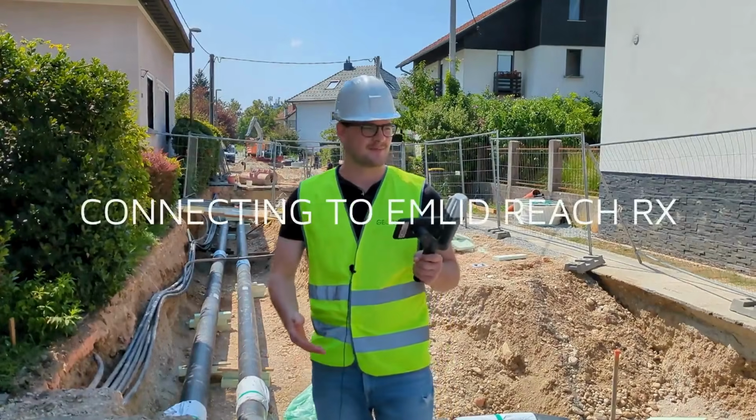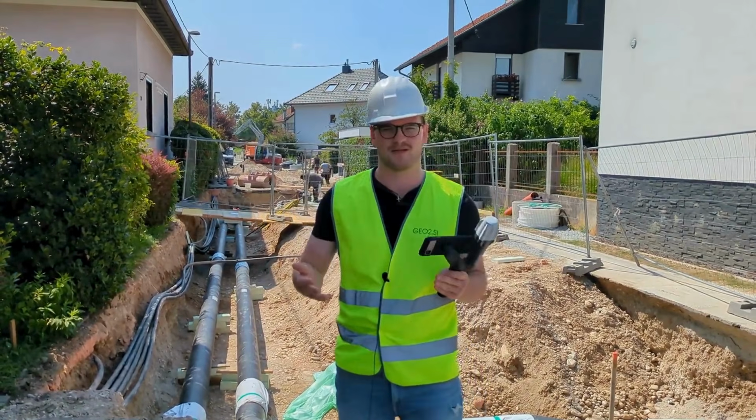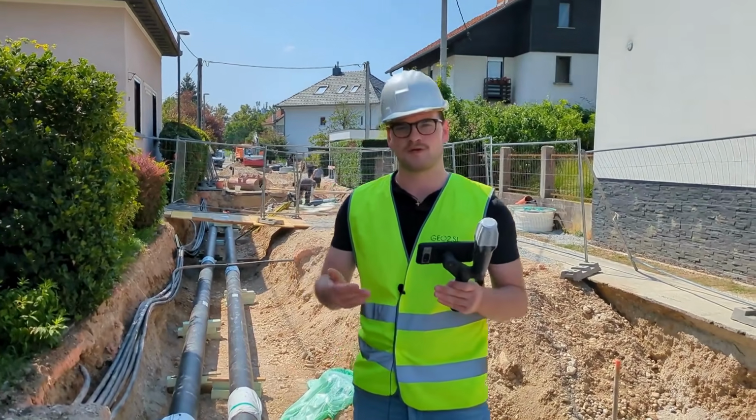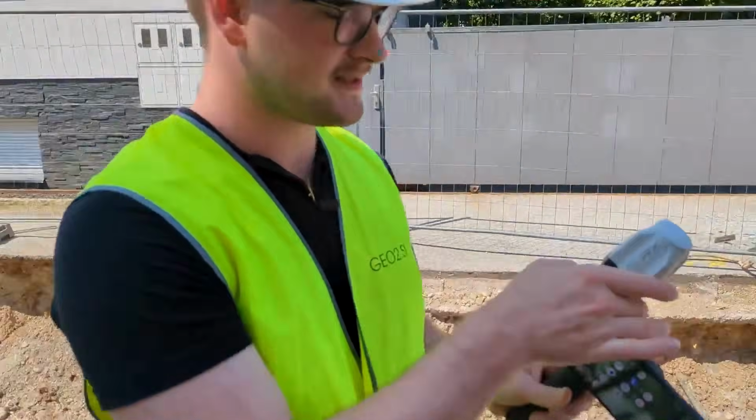So as you can see, I have spread the April tags across the construction site approximately equally, so we are covering the whole terrain. Now let's get to the recording part. First, we need to power up the Emlid Reach RX.